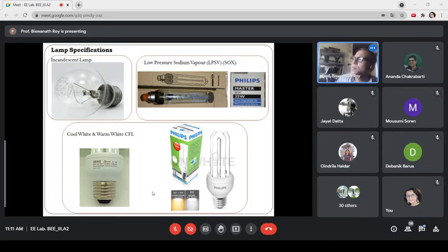And also in a room, an interior space finished with wooden color or a similar kind of structure, a lamp that emits warm white color makes it more vibrant, more matching. So these are very special types of application, and in those applications, warm white lamps are preferred, although lumen per watt conversion is a little bit less than cool white.